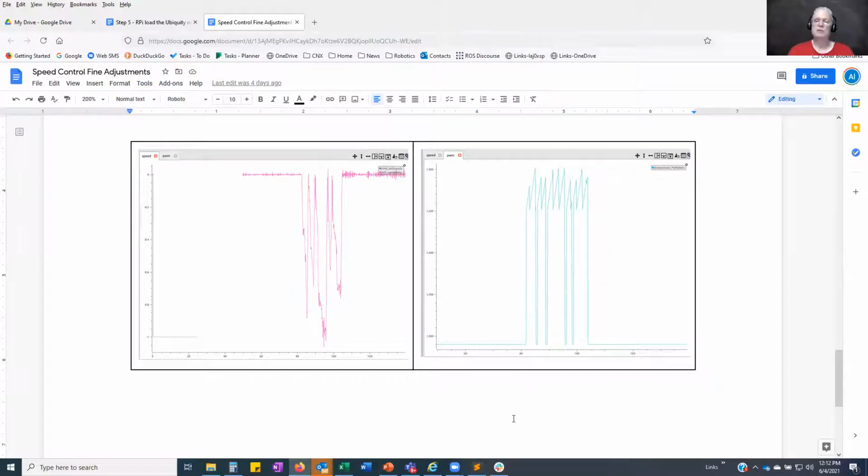What I did, I just put my mini tractor out in my front yard, and this is the electric one, not the gas powered one. I went into my code where if you issue a command velocity it has a timeout that says after half a second or whatever, shut the speed down to 0. I just moved that number out to like 5 seconds. So I could type in one command velocity message, supplying a forward velocity and a steering angle, and the thing would start up and drive until the timeout. It would just automatically stop.